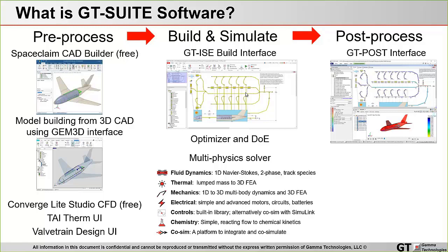Now, once the solver is called, it calls our multi-physics solver, which allows users to integrate at will different physical domains, including starting with fluid dynamics. Our solver is backed by a 1D Navier-Stokes solver that is two-phase capable and can also track species. And we'll get into a little bit more about what that means in a minute.